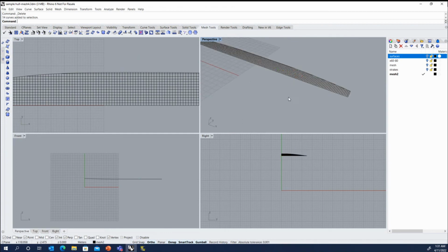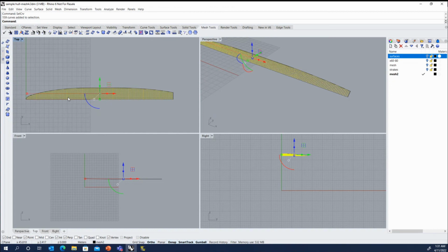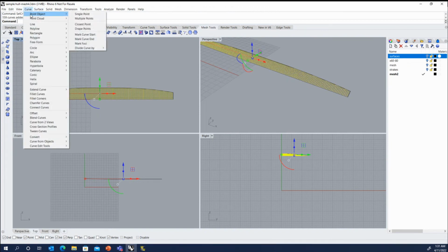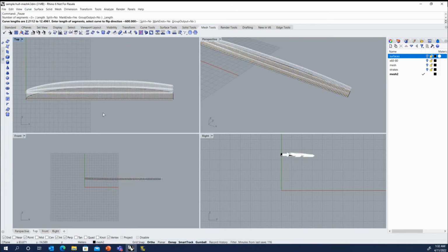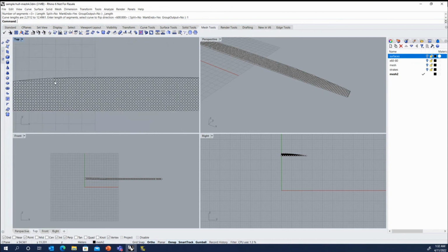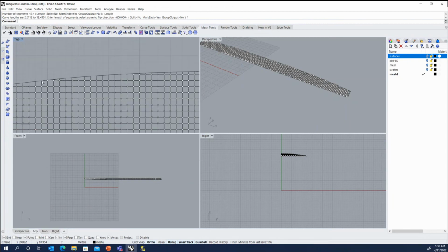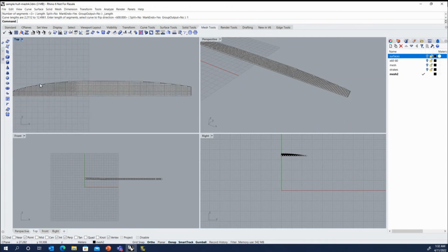Now, if we didn't want to do contours, another method of getting those, and this is similar to the girth method that's used in that script. If you didn't want to actually generate the mesh, if you only wanted the points, a similar way of getting it would be to go into the curve point object, and previously we used the number of segments, but if we were to use length of segments and specified 1 meter, you can see we got a very similar collection of points to what we did with the 1 meter contours. Now we deleted a few at the ends there. You can see which ones were missing, but that would be another way to create those.